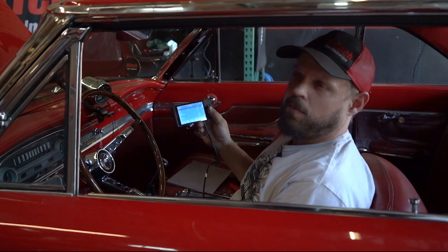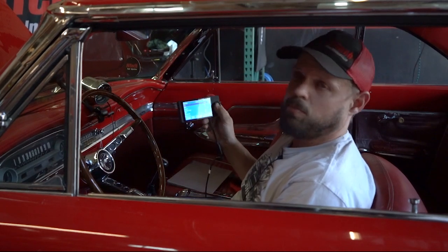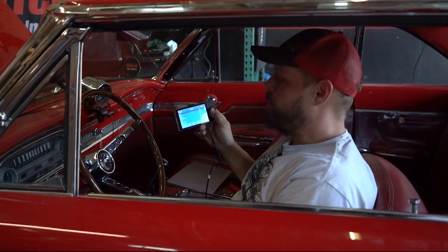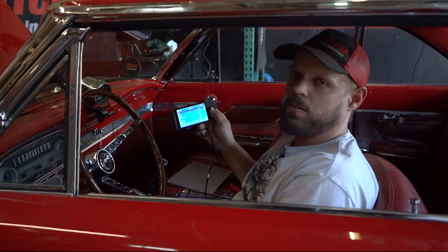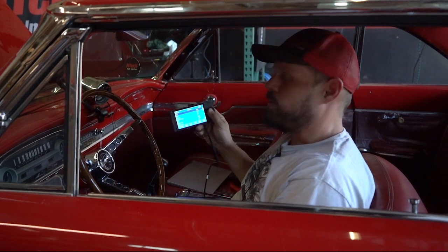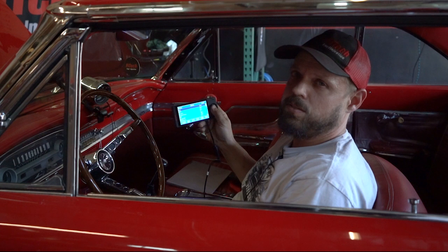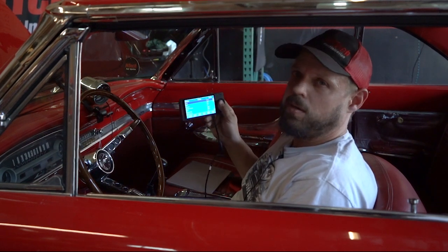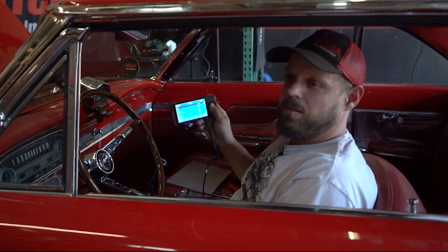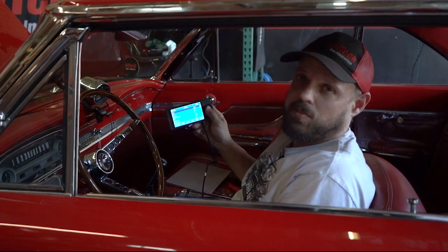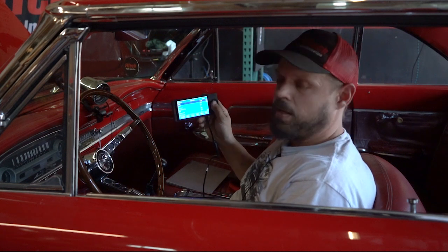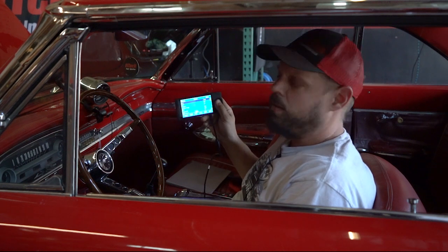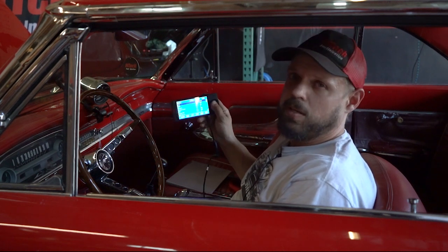So there you have it. AFR learning and trim is important for the system operation. That means you do have to run with your oxygen sensor all the time, but that makes sure your engine's operating at ideal conditions all the time and that the system can make all the corrections that it needs to do. If you don't have your oxygen sensor working properly, or if the trims are way far off, you may hear the engine stumble. It may have a little hesitation or smokiness if it's really rich, but getting those things dialed in right with the learning doing its own thing is fairly important for the operation of the engine.